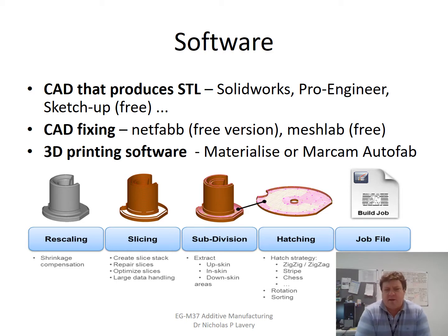The STL file is possibly not the best format that could be used. STL is a very simple file format, which has a series of triangles which mesh up the entire surface. But sometimes that simplicity itself is its downfall, in that a triangle can be missing and you end up with an open volume, and there's no volumetric definition within the STL file.